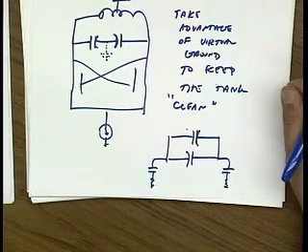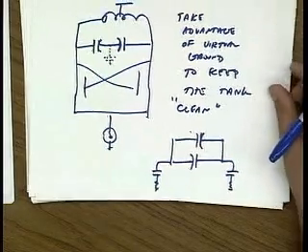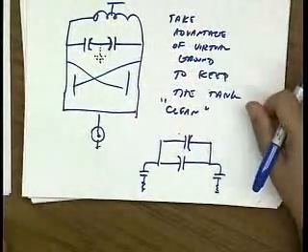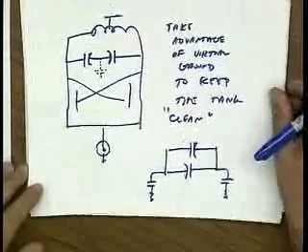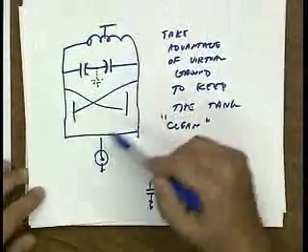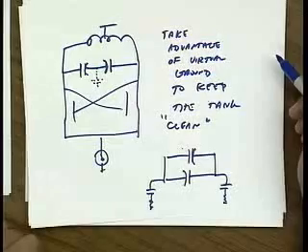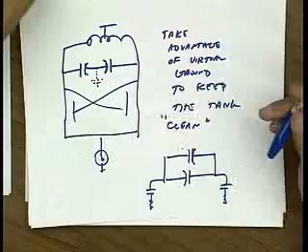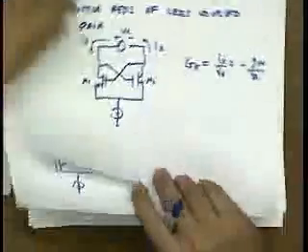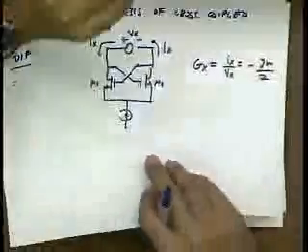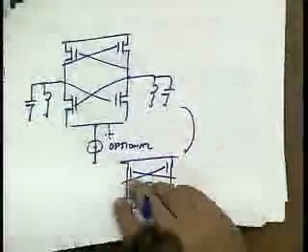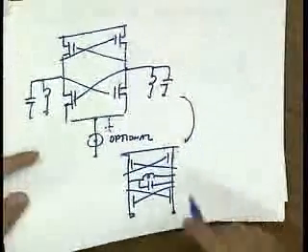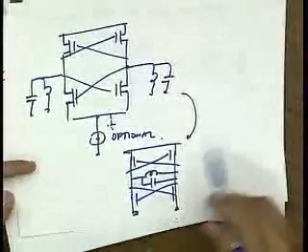Okay, let me say also a few words about, so this is pretty much the topology of choice. If you look at papers or products, and if you could actually peek inside and look how they implement their oscillators, they're usually differential oscillators. If they're MOS, they're implemented either like this or something like this. Actually more like this. And if it's bipolar, instead of having a direct cross-coupling, you'd have a capacitive feedback.